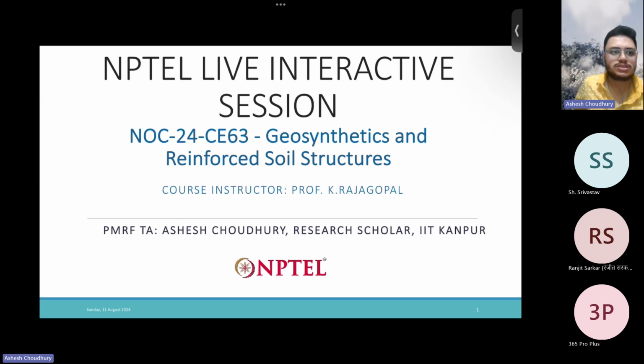Okay, so just directly, in the place of sigma r you have to put 60 kPa, and in place of Ka you have to put tan squared of (45 minus 33 by 2), that's all. If you put everything in, you will get the answer, I think, 55 point something. Okay, 55.3 kPa, you will get the answer. This was a very straightforward question where you just have to use the relation directly.